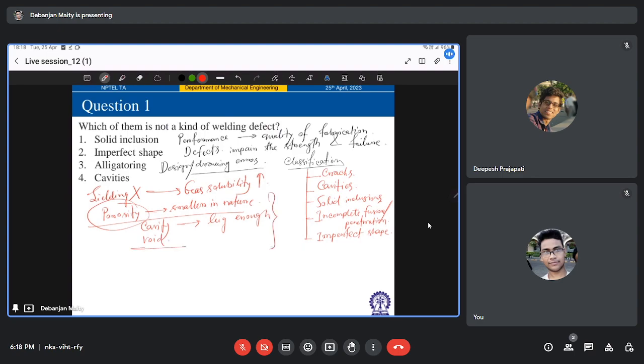No, so the physics is a similar kind of thing. Because of this entrapment of gases, or there can be hydrogen entrapment in the liquid melt pool, if your solidification time is very fast, then this gas entrapment cannot get enough time to escape from there, right? So the porous structure will form from there.